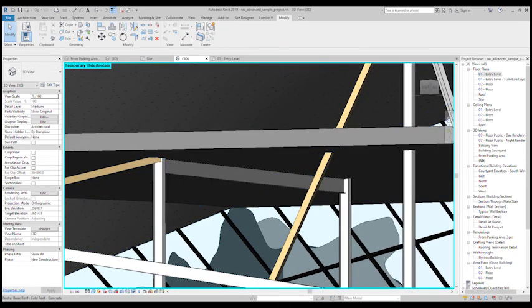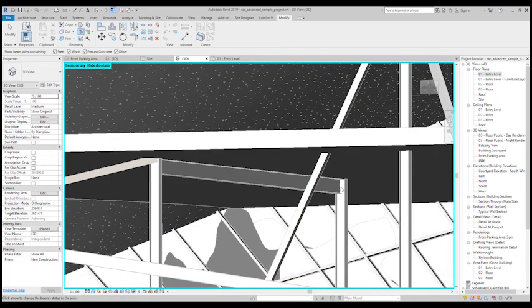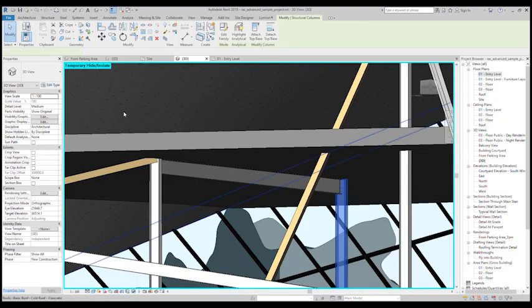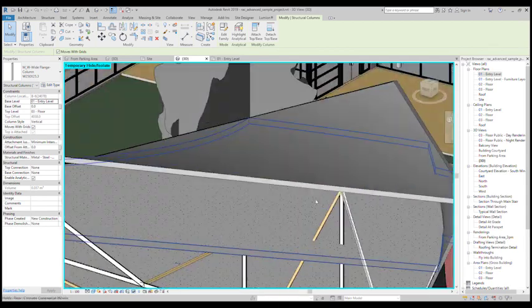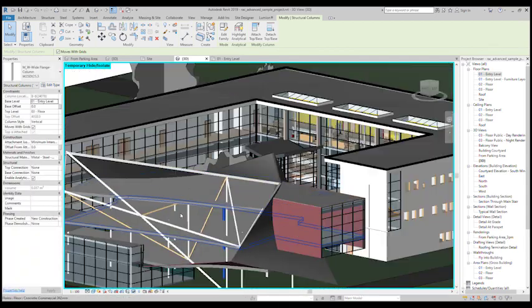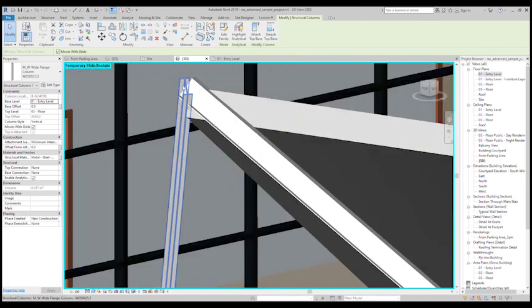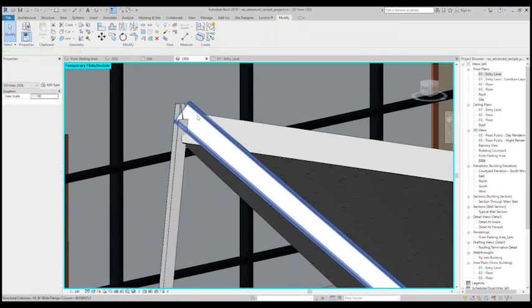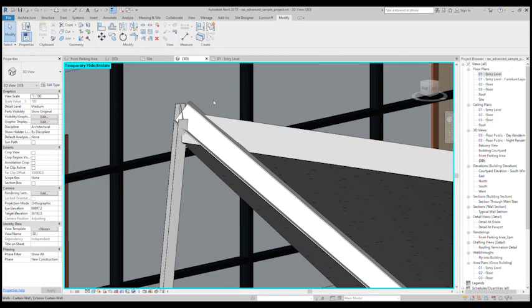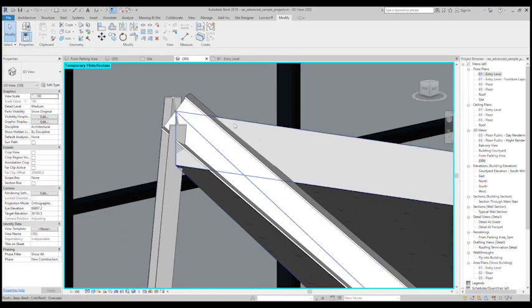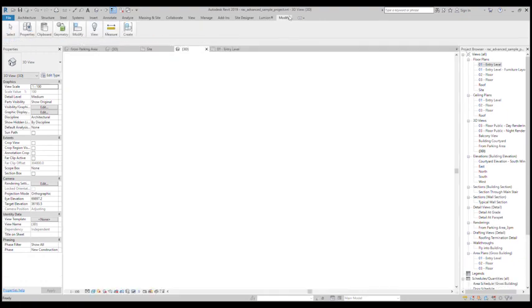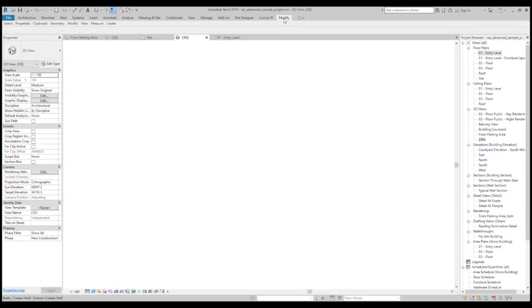Maybe now if we say no, it needs to be the same family, exactly the same family, and it needs to be the exact same shape, then you can do different connection joints, which I kind of don't like, messy joints like this. There is an option called coping, which you cut steel beams with another one or columns with another one. So you click on, you go to modify. Sorry, I just need to reset that.